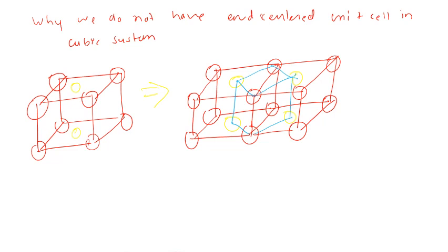This is a different unit cell I can draw with the help of the end-centered atoms and the cubic corner atoms. This unit cell is known as the simple tetragonal unit cell. For any unit cell the criteria is that it should have higher symmetry and the lowest volume possible. So from the end centered cubic unit cell we can draw a simple tetragonal unit cell.